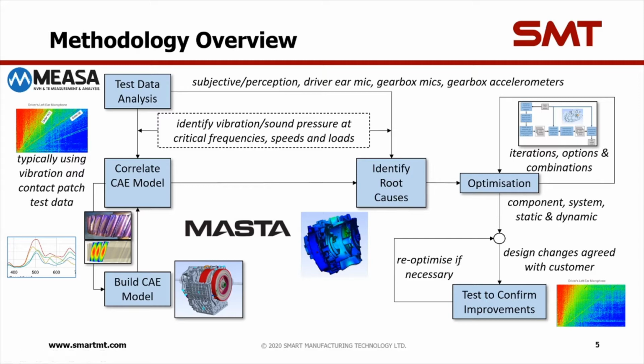So we will start to look at and simulate the system behavior: deflections under load, looking to predict gear misalignments. We will examine the gear geometry. Is a further optimization of the gear geometry possible? Then we'll simulate TE and other excitations and compare them to best practices, followed by analysis of the transfer path and system response.